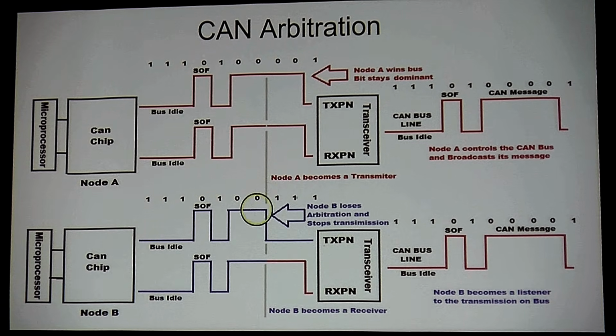Now, when this guy falls and he becomes a listener, this guy goes over and he held 2 more bits, and then he falls. Well, when his voltage drops at this point, and I get a drop on the read, now he knows he commands the bus. So now that he won arbitration, he's going to go ahead and send his message and his data. He's going to send an identifier out during the arbitration. So he's going to say, I'm the ECM, I'm the ABS, I'm the transmission controller. There's going to be data in this field right now, and this data is going to say who he is and what he's doing, right? So this is basically how I'm going to win this arbitration. Now, he's got control at this point.